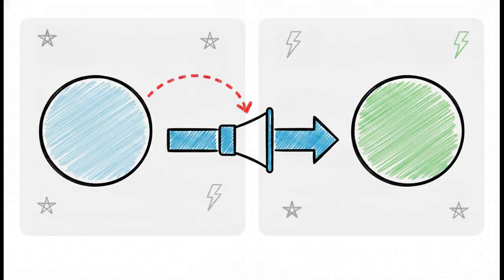And this brilliantly illustrates the crosstalk between the ports. Take a look at Z12 and Z21. Z12 tells us how a current applied way over at the output port reaches back and messes with the voltage at the input port. On the flip side, Z21 tells us how the input current influences the output voltage. That Z21 parameter is incredibly fascinating because it essentially describes the forward transfer characteristic, which is absolutely vital when you're analyzing how amplifiers and transistor circuits push signals forward.